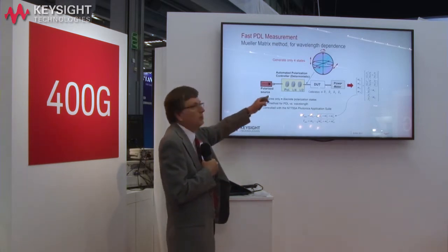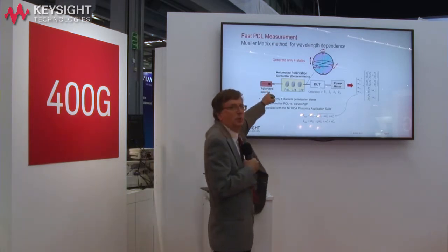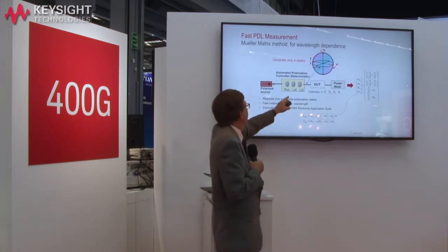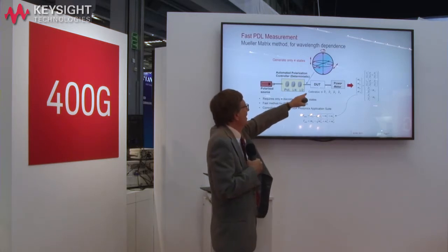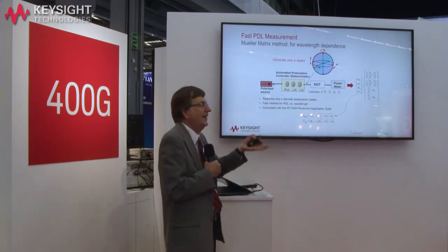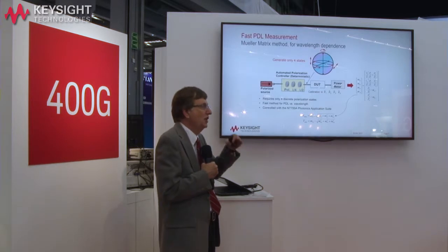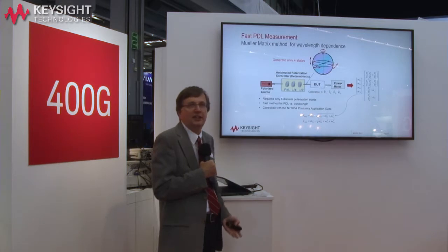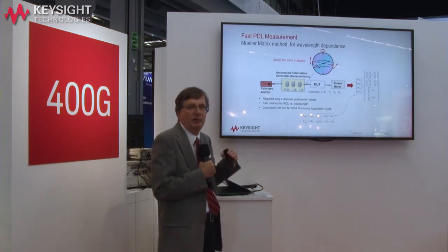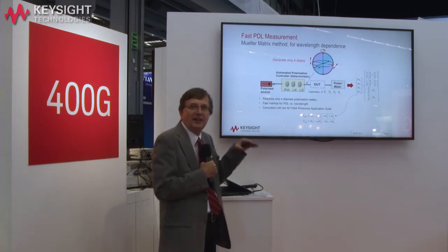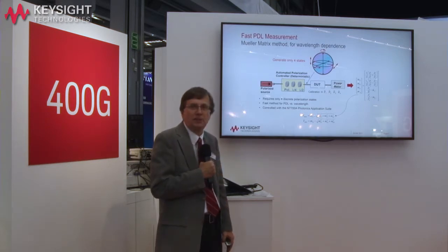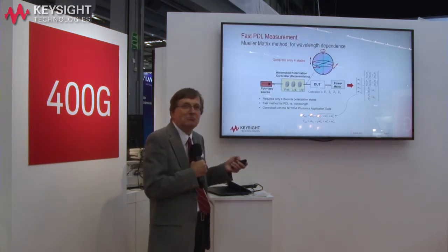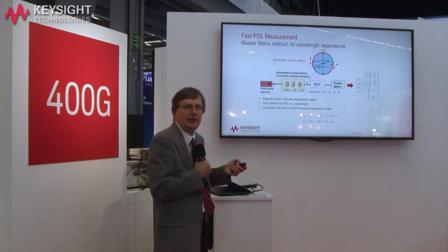which makes swept measurements. Now we can take this polarized source and sweep with a certain state of polarization and then measure how much power goes through that, then do the same thing at a different state of polarization and a different one. With 4 states, we have enough information to make a matrix calculation and determine the maximum and minimum without ever having had to reach that state of polarization. That turns out to be very useful. That's a state-of-the-art technique for the industry.